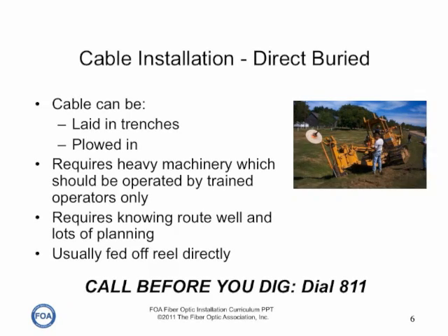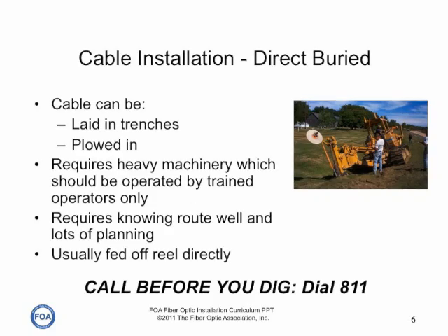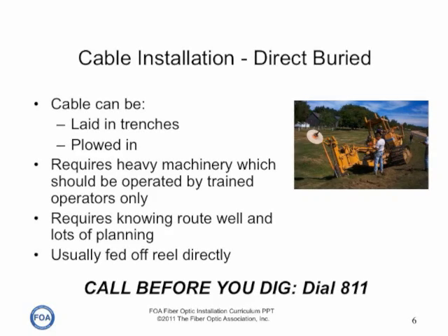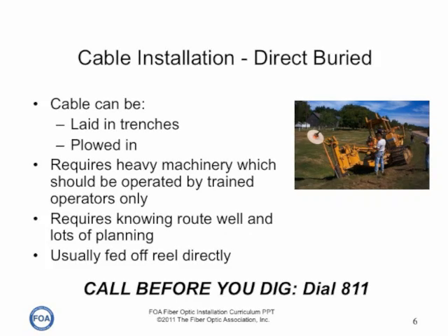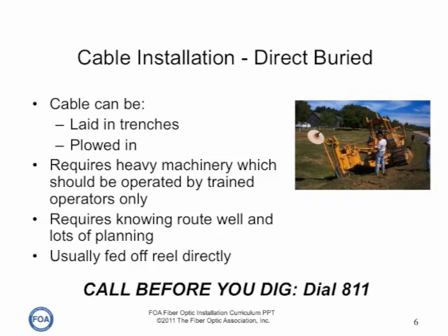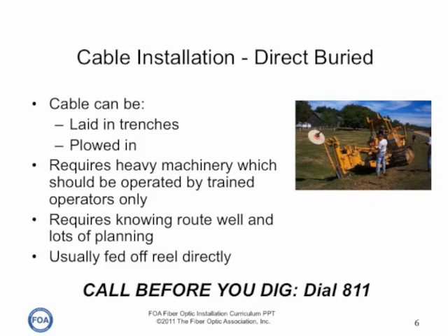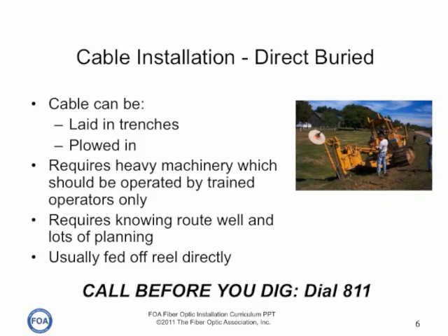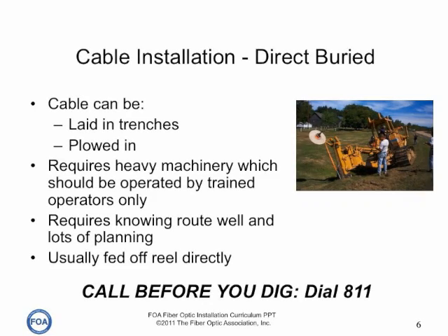cables. It's especially important to know what kind of cables and pipeline are already buried in the area, because it's very dangerous to dig up, obviously, other cables, or even more so, it's dangerous to dig up things like gas pipelines. There is a number you can call before you dig and find out what is in the area. Just dial 811, a toll-free number, and ask about the area you're digging in.